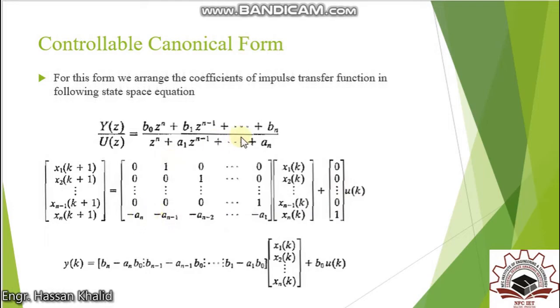Now if you observe this G matrix, you can easily place those variables from the characteristic equation of the given pulse transfer function by placing all those coefficients from a1 to an in reverse, negative direction.